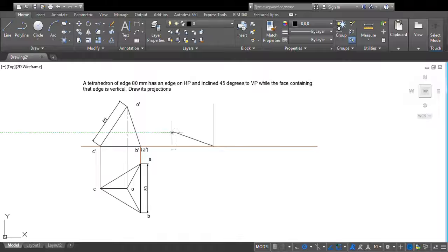So you got that line. You can complete that triangle. Here what we are doing is, first we are drawing this line vertical like this. This length, same length line vertical, then this angle and this length line you are marking this side. This angle is 71 degrees, and this length is 69 mm I am getting here, so that length I am marking here.